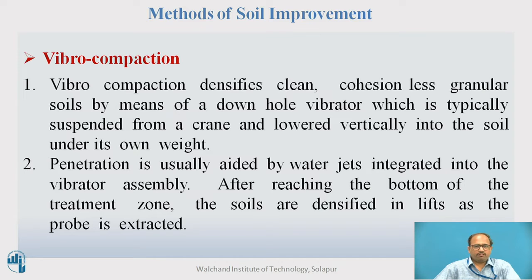We will attach one water jet along with your vibrator. After reaching the bottom of the treatment zone, for example, the depth is 1.2 meter, the soil is densified in lifts as the probe is extracted.